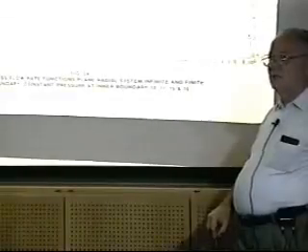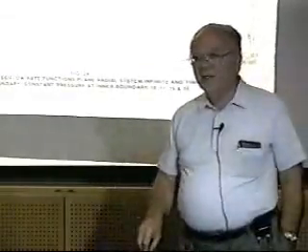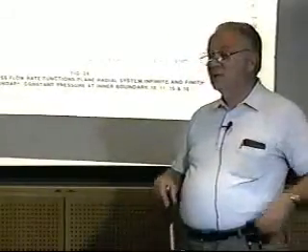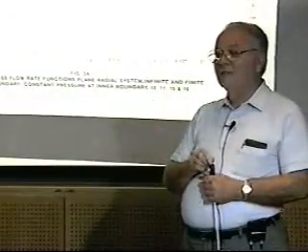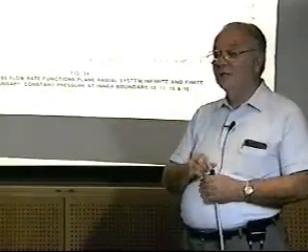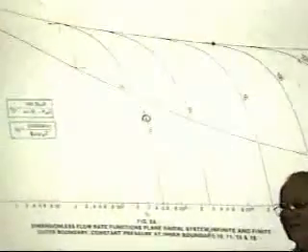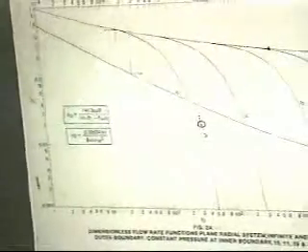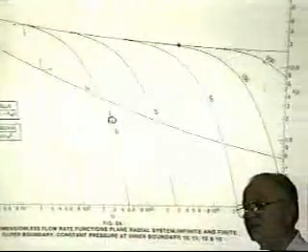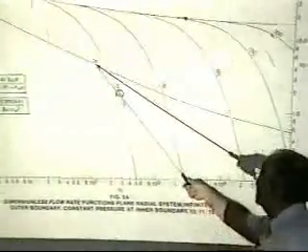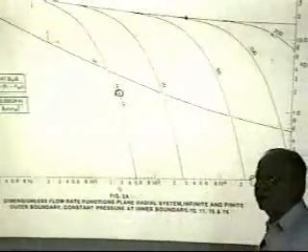But in the early days when we were in Bartlesville and we'd get data in from the international department overseas, the data came in on a telex. So you had a tabulation of the production rate versus time. And I can guarantee you a low permeability successfully stimulated well looks very, very bad in tabular form on a telex when management's the first ones to get it, and then the engineers get it. And the very first interpretation everybody makes is depletion. It's very easy to plot the data log-log to tell if you're on a transient or on a depletion.